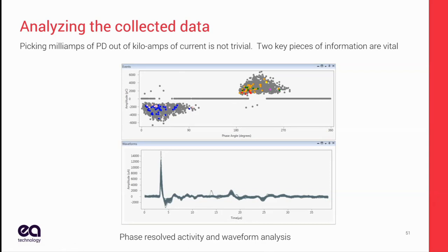What we are looking at is that we've got 2 groupings, half a cycle apart. Opposite polarities is really good, right? We got something on a positive half cycle and something on a negative half cycle. Each one of these dots represents a capture that we took, and so clearly something is going on in this picture that is synchronous with the 60 hertz, synchronous with the power system frequency, and is occurring twice a cycle and is opposite polarity. There aren't many things that'll do that. That's a very clear picture.